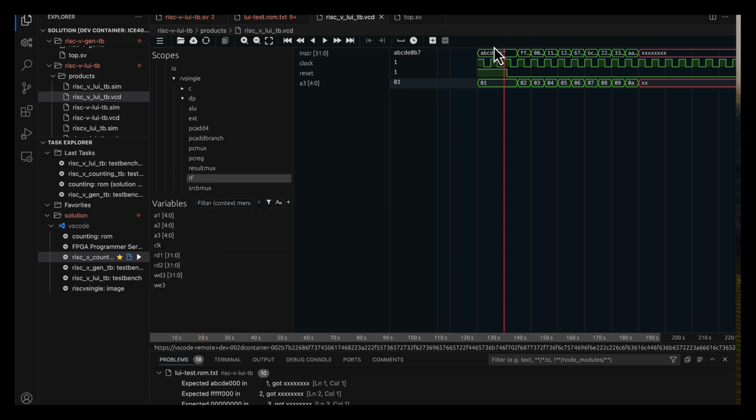What about the data? Is this ABCDE actually being sent in to be my write data? Let's add that trace in. Oh, looks pretty good. So I've picked where I want to store it and what I want to store. But something must be going wrong. So I guess the third part of storing things in a register would be actually specifying we want to store it using the write enable. And there I found my culprit. I was never actually asserting the write enable signal.